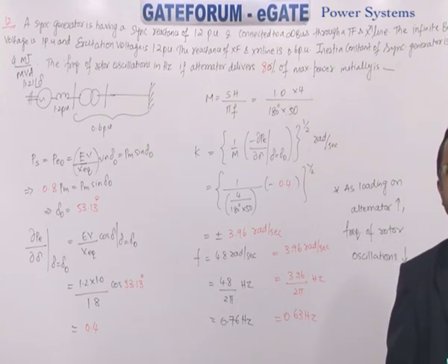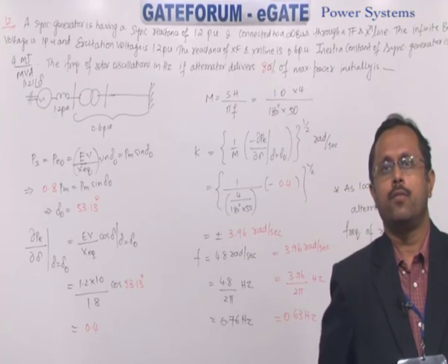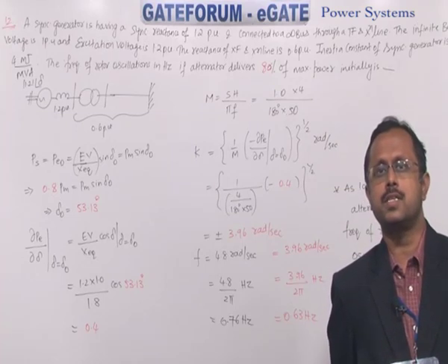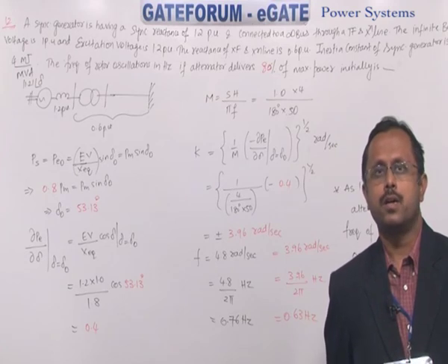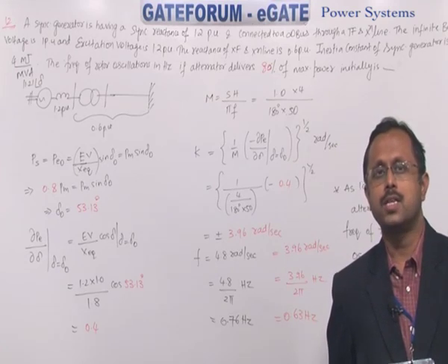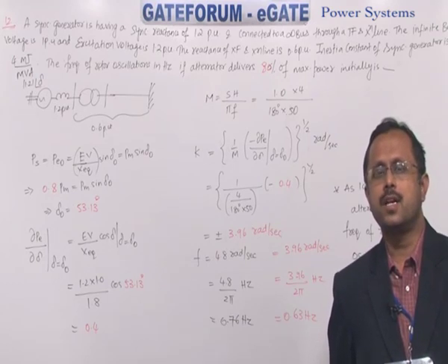Now we have a few questions. First question is by Purushottam from Jaipur. Why with an asynchronous machine is the PA equal to 0 condition not achieved? Because you don't have any control regarding the shaft input, the steam input. With a synchronous machine you can achieve that condition.